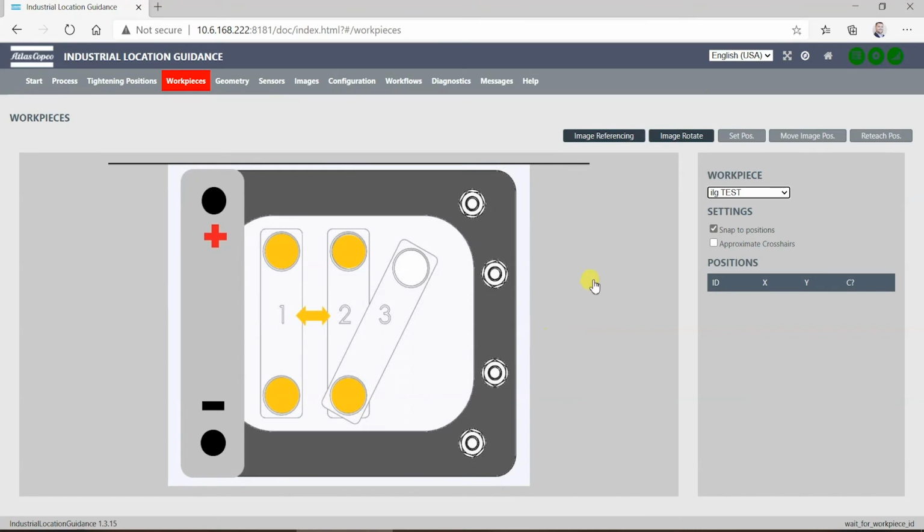So the first thing you're going to want to do, what I find to be the most useful, is the snap to position. And essentially what that means is as you're bringing either the torque tube or the arm into position, if there's a little bit of movement, you don't want that to be clicking in and out of position where the operator can't get on the bolt. What you want that to do is to snap there into that position and then turn blue. So this is giving you a little bit more of a space to be able to get on that bolt. Now, it's not going to allow them to run if they're not in the right location. It's just going to give a little bit of freedom to the operator as they're on that bolt, getting to the spot where they need to be.